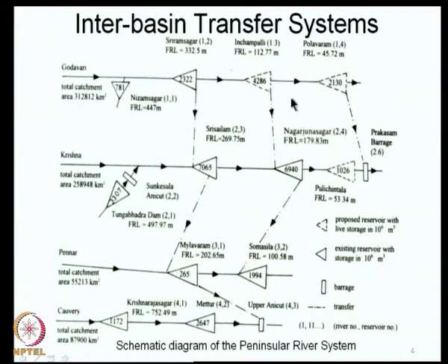You know the flows that are coming there. Then you start meeting the demands. If there is a deficit, you go upstream and check whether you can meet the demands from the upstream reservoir. And then one by one you keep moving in a certain direction, either from downstream to upstream or upstream to downstream.